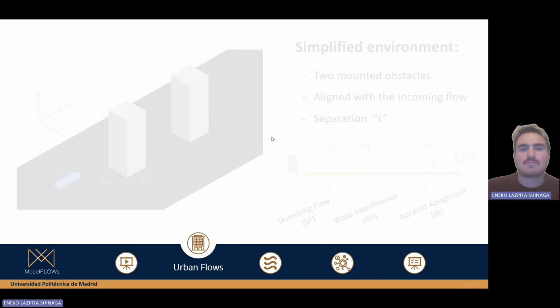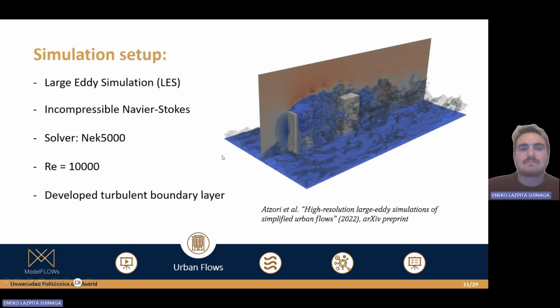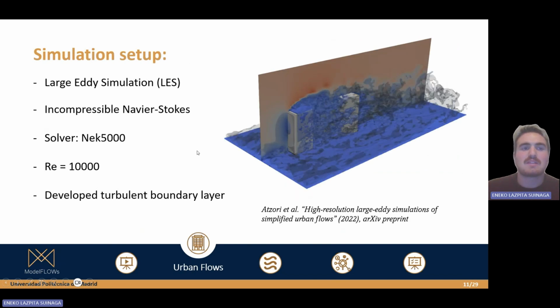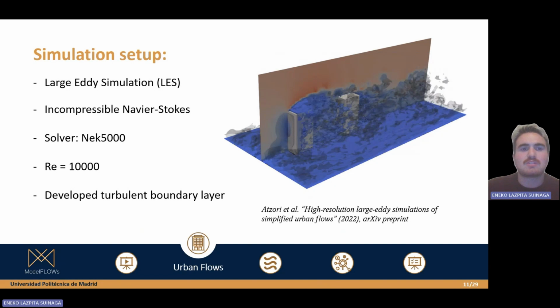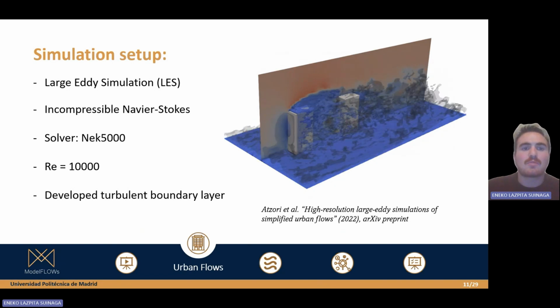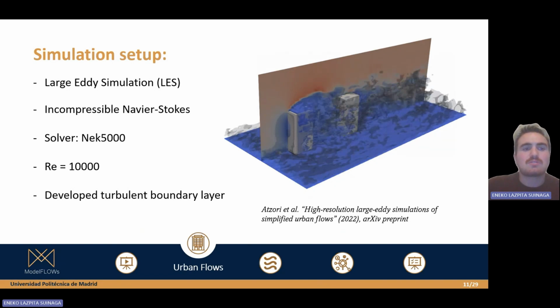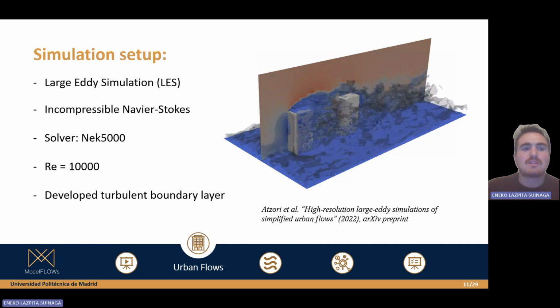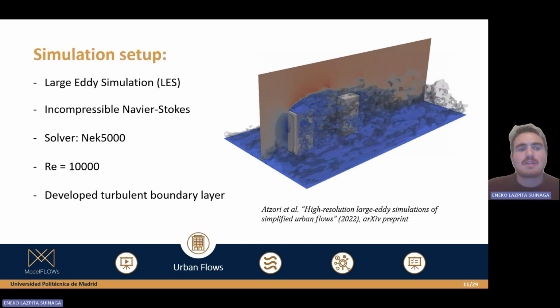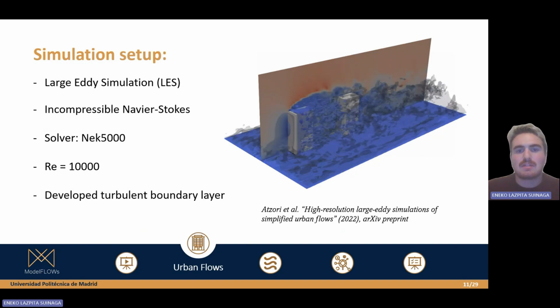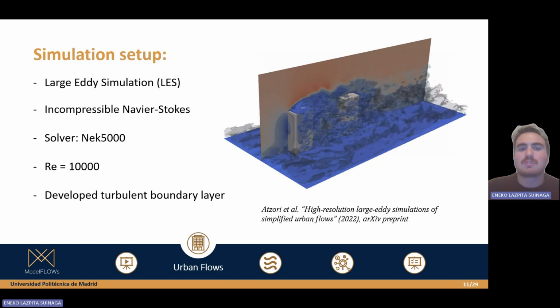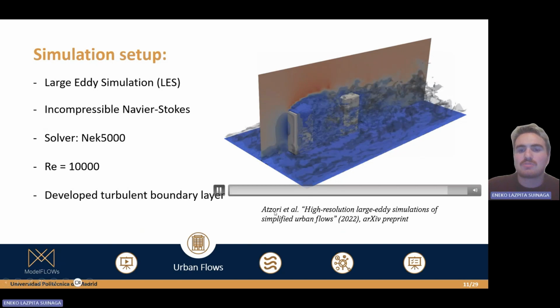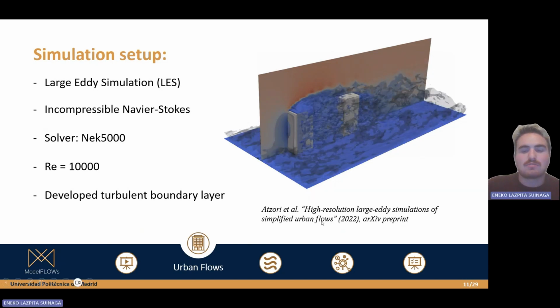Our simulation has been done using large eddy simulation, LES, with the incompressible Navier-Stokes equations. The solver we have used is NEK5000. The Reynolds number is 10,000, and the inlet condition is a turbulent boundary layer. For more information, you can go to the link to the paper you see here.